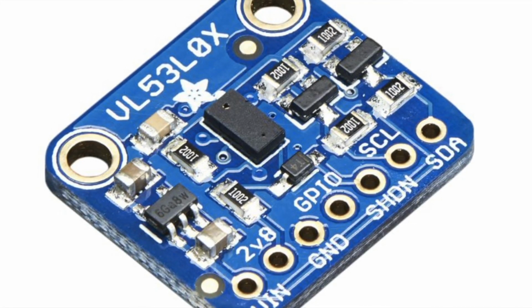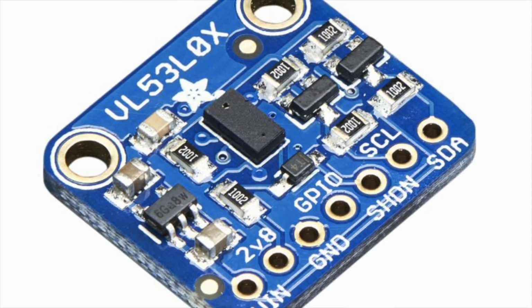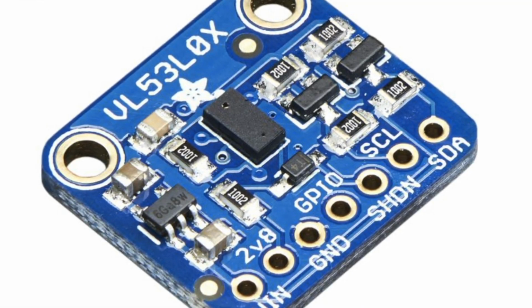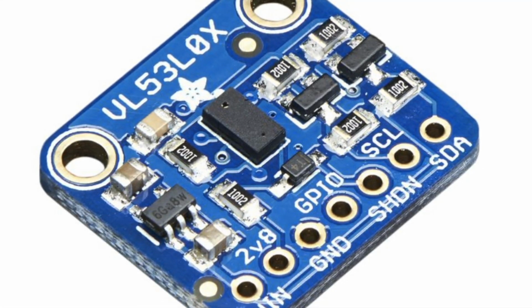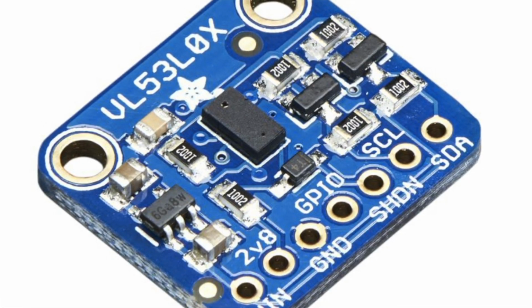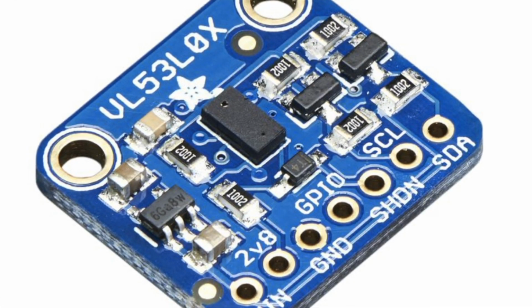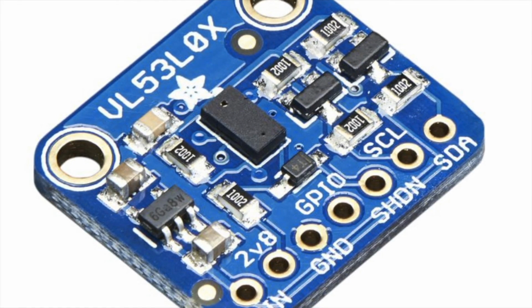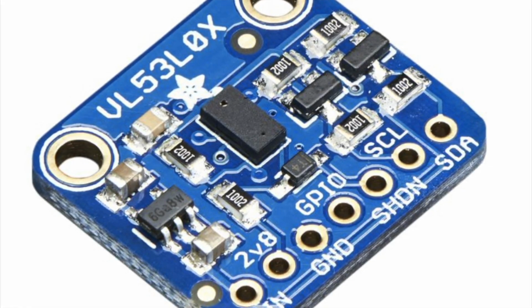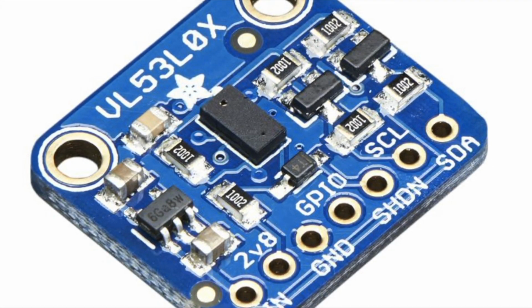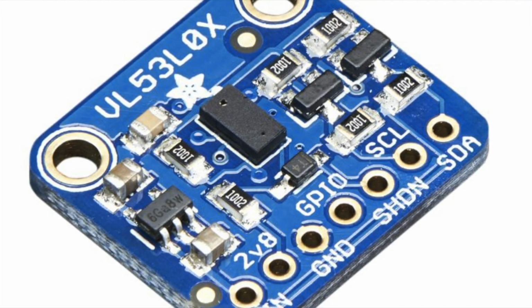And it can also be used to measure distance if you need to measure how far away things are in a linear fashion. However, its field of detection is very narrow, so it only measures things directly in front of it. If you need to monitor a small area rather than a narrow, single location, the ultrasonic sensors might be a better choice.